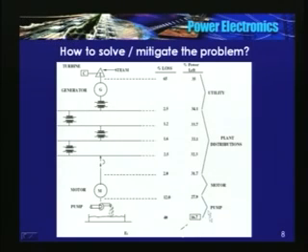So the question is, why spend much effort on motors and their equipment when the losses are at the front end? Why worry about improving the conversion efficiency of the equipment or the machine, when the bulk of the loss is at the front end or at the turbine end itself? See, the answer is very simple. Every kilowatt of power that is saved at the process end results in saving of 6 kilowatts of fuel energy here. 1 kilowatt here is equivalent to 6 kilowatt here.